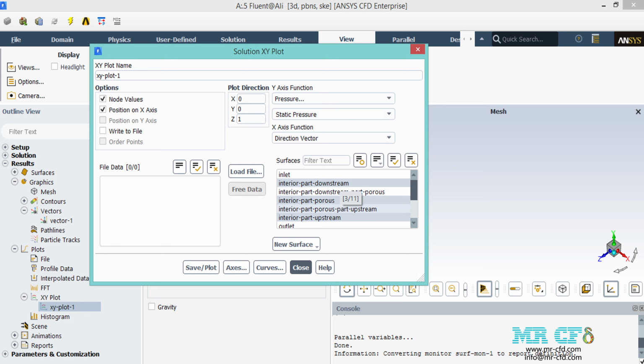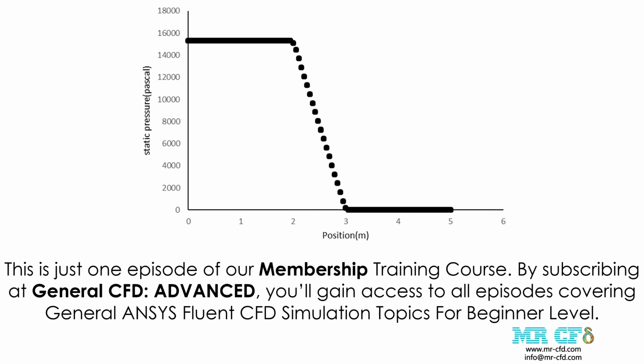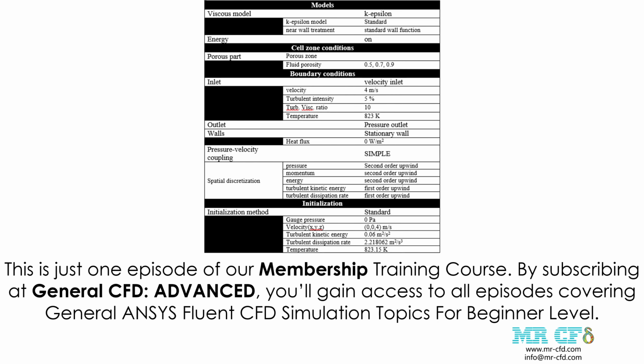Now for creating the pressure drop plot, you just have to change the plot direction by changing the Z value to 1. After that, by clicking on the interior part, downstream, porous, and upstream, a plot will appear showing you the pressure drop in these zones. Finally, a summary of different settings and setup that we have used in our project is presented to you in the slide.